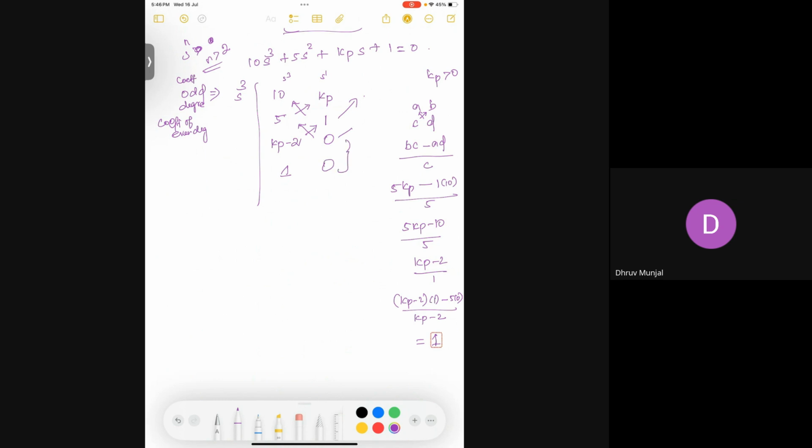Now these two become 0. So I'm left with only one element. So I'm stopping here. This will exactly give you the coefficient. And after this, you cannot proceed. Every time you will be left with 1 when it becomes s equal to 0. Okay. So now I have said that all coefficients of second order polynomials should be greater than 0 for the system to be stable, right?